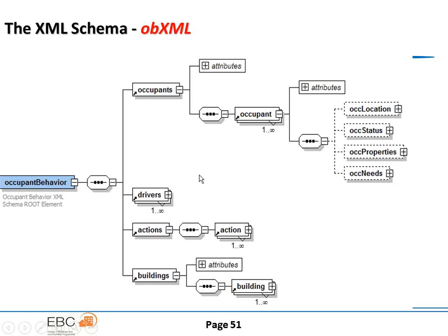But in EnergyPlus, you can also use the energy management system, which allows you to write code. Quite tricky though, right? You have to spend lots of time debugging and understanding the whole system architecture. But now there's also another option. If we package the behavior model we're talking about into a software module, and then allow co-simulation through the functional mockup interface, it can be used with EnergyPlus, and even with your Excel spreadsheet if you just want to develop something in-house.